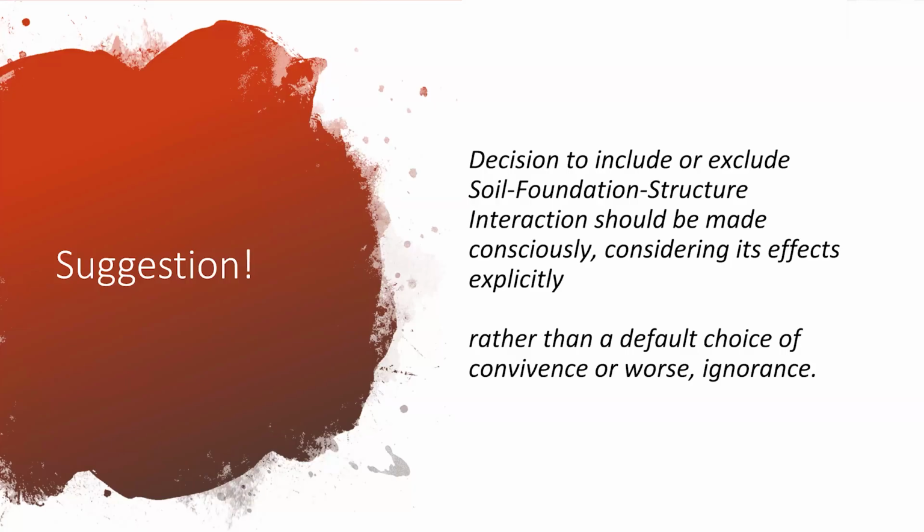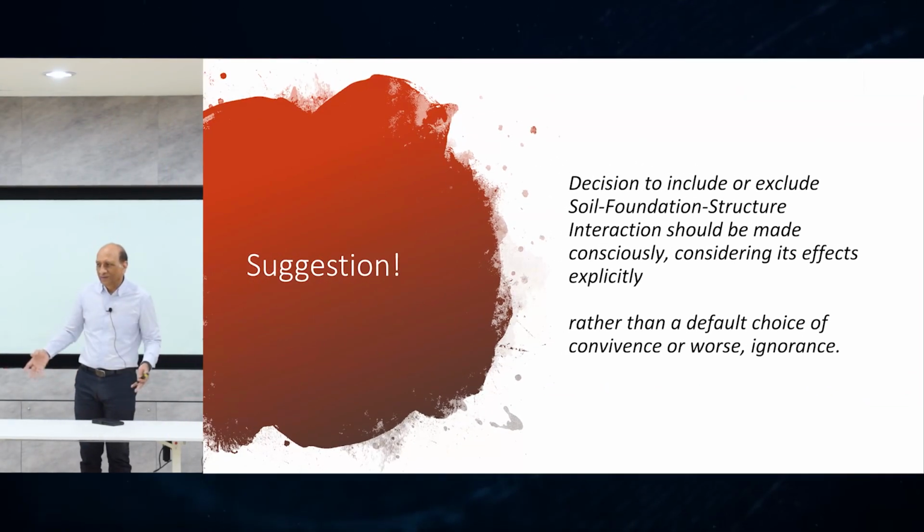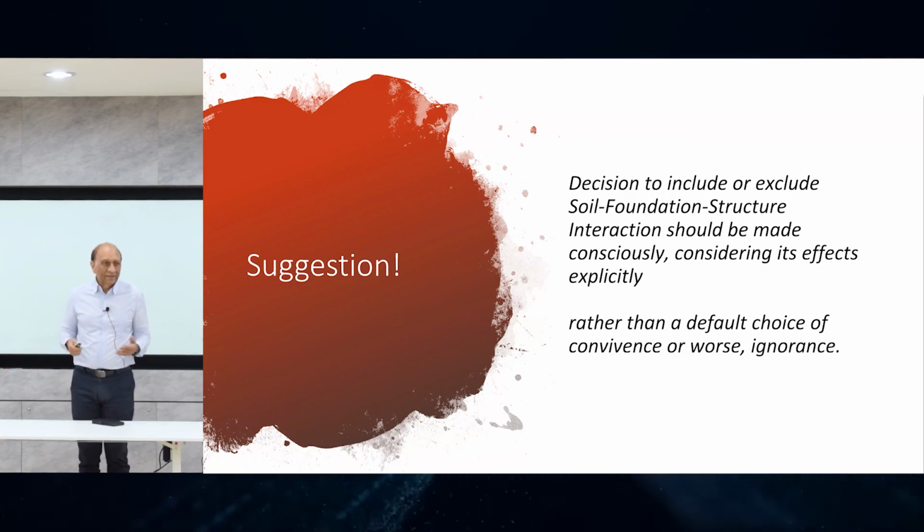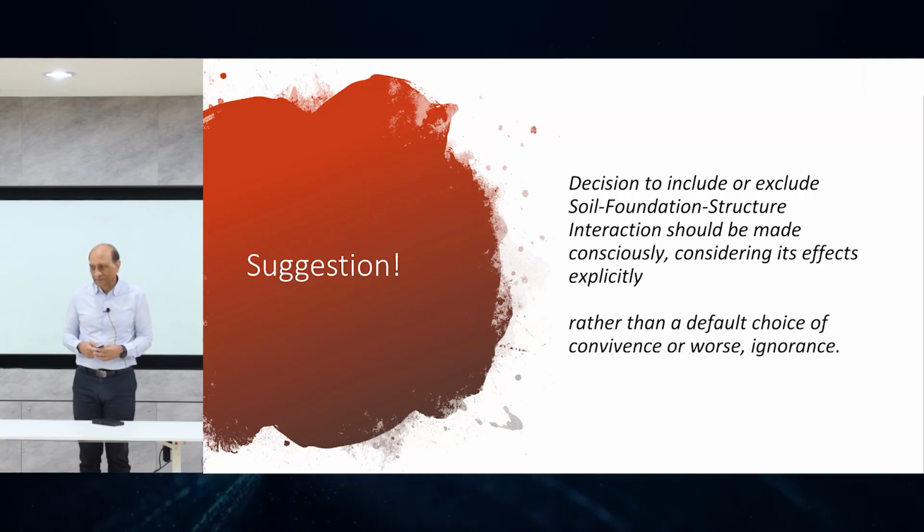All right. The decision whether we include the soil structure or not is something people always think about. And like I said, my feeling is that the minimal soil interaction should be included in any case, because it doesn't cost you anything else. Just put the foundation there, put the soil there. Don't ignore it. You're modeling everything, and there's a column below that. There's a huge raft. How can you ignore it? Or there's a footing. How can you not see it? So don't just stop at the base of the column. Go down, and then replace the soil by springs and in some cases nonlinear elements. Okay.